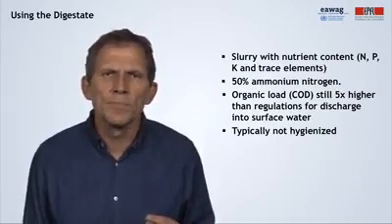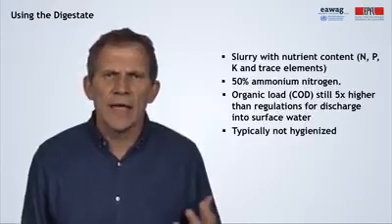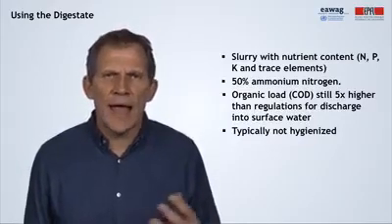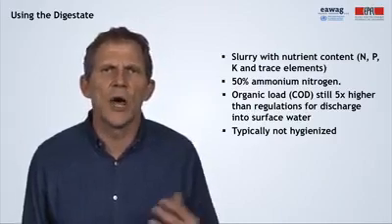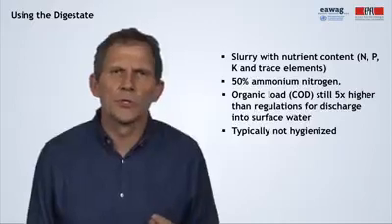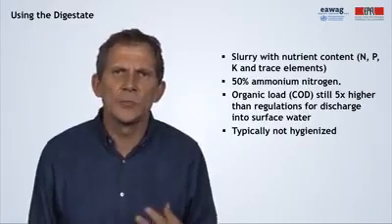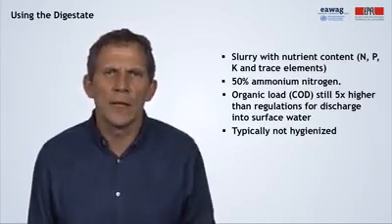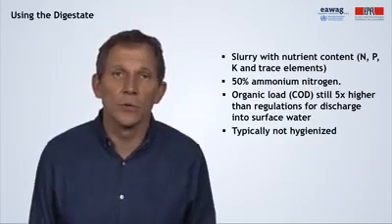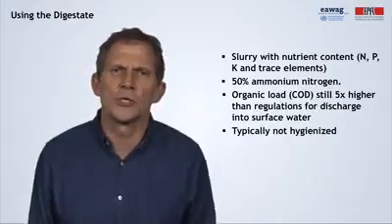But remember, in the mesophilic range we don't have high temperatures, so if we have pathogenic substances, these are not hygienized. If it is not possible to use this digestate in agriculture, then the digestate has to be treated before disposal, as it still has a high organic load and, based on regulations, would not be allowed for discharge into surface waters.